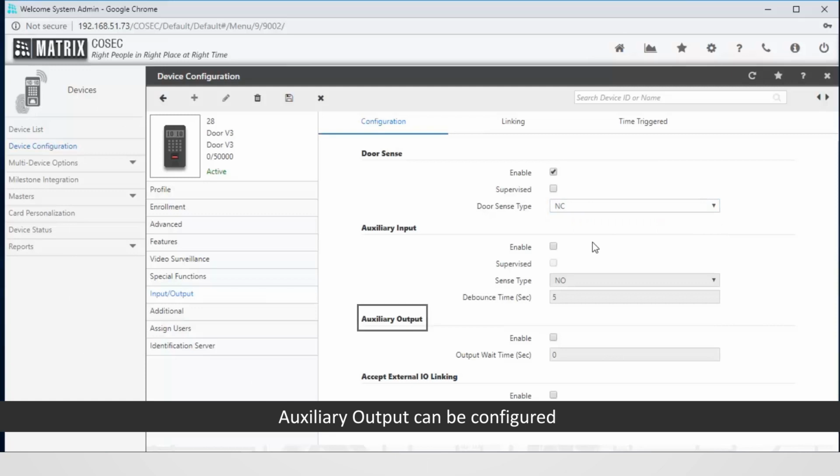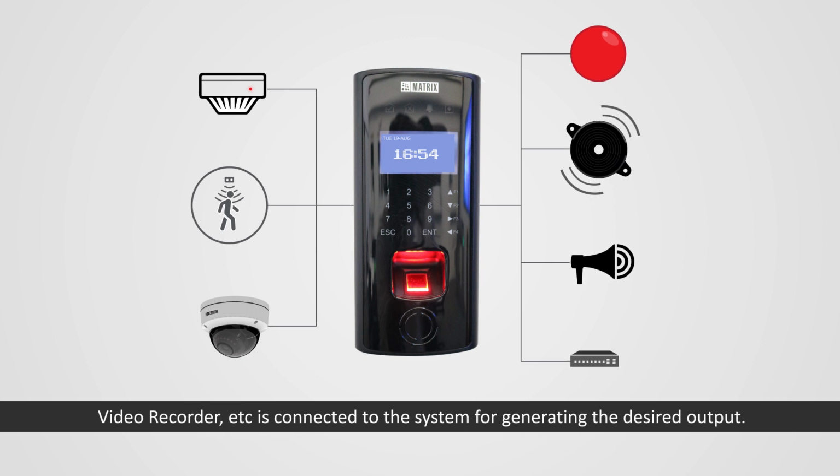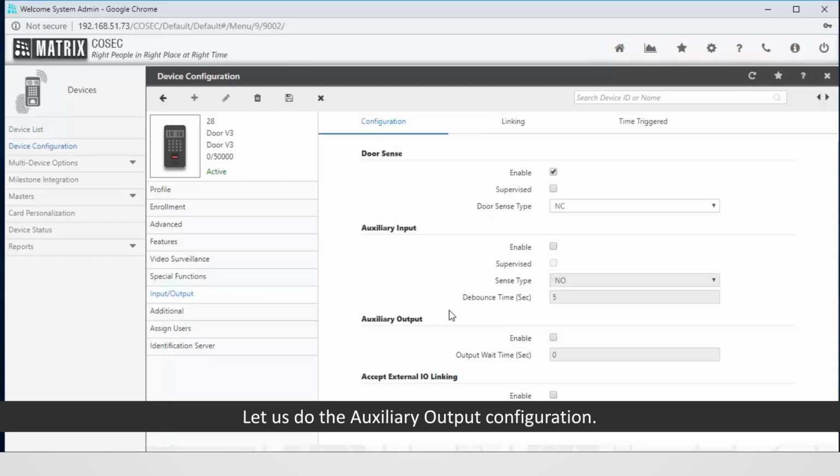Auxiliary output can be configured when an output device such as LED, buzzer, siren, video recorder, etc. is connected to the system for generating the desired output. In our case, the red LED is connected to the AUX output port of the device. Let us do the auxiliary output configuration.